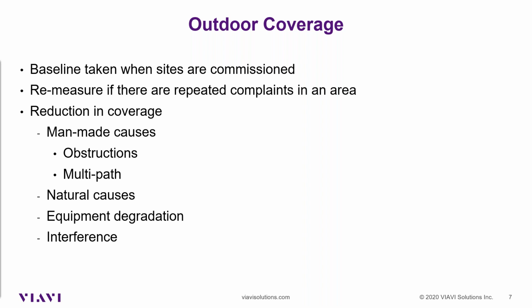So multipath is another thing that I think a lot of times is overlooked. It's easy to look at a situation and say, well, the signal level is low, so obviously that's the problem. But if the signal level is fine, then we start looking at other things. Well, is our programming right? Is something misaligned? Is there some other sort of failure? But multipath, I think, frequently gets overlooked, and it can cause some very strange behaviors.